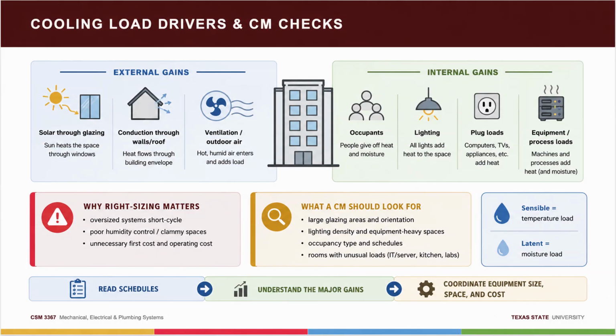Quick drill, call and response. Three minutes. Let's drill it before we move on, because the quiz will make you sort loads, and I want this automatic. I call out a heat source. You call back sensible, latent, or both. Ready. Sun beating on the roof. Sensible. Pure temperature, no moisture. A packed church congregation? Both. Bodies always give both. Skin heat sensible, breath and sweat latent.